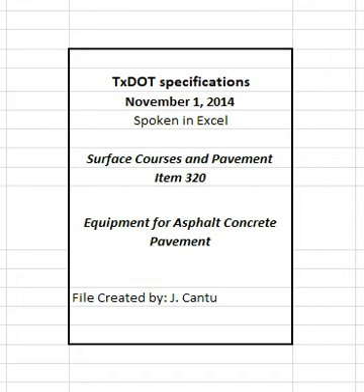2.3.1.2 Screed. Provide a heated compacting screed that will produce a finished surface that meets longitudinal and transverse profile, typical section, and placement requirements. Screed extensions must provide the same compacting action and heating as the main unit unless otherwise approved.